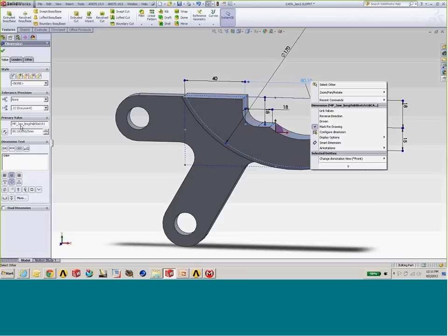And in addition to that, I want to rename my parameters such that they have a recognizable name. Now, the reason I do this is when I bring geometry and parameters into the analysis environment, there's no way other than trial and error for me to figure out what the relationship is between a particular parameter and the geometry. ANSYS doesn't know that. And it relies on the CAD system to keep track of that because that's where the original features and parameters are linked together.